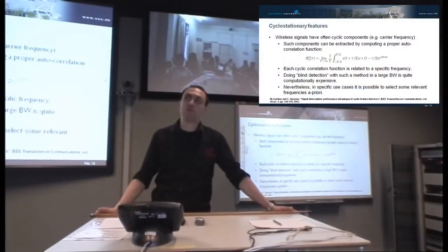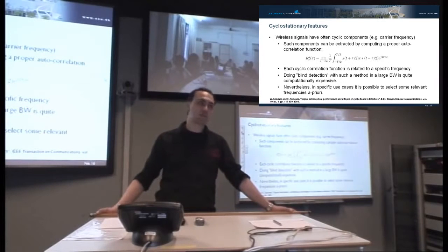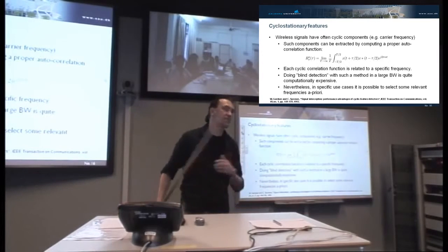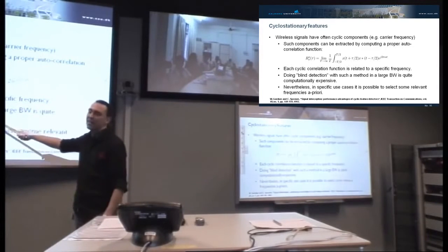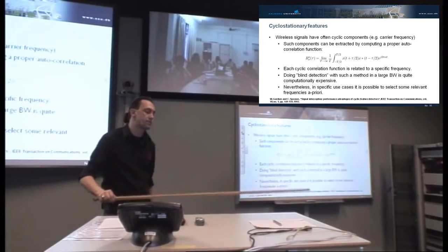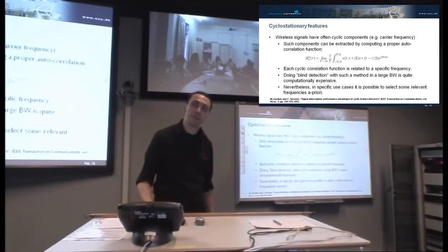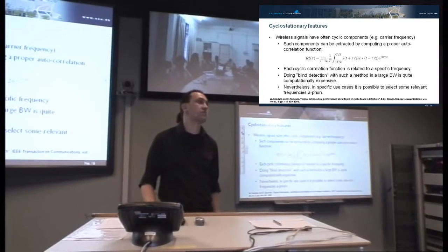If you want to do blind detection of all the cyclic frequencies, so the frequency which is always there, in a wideband, forget it. Because doing blind detection with extracting this type of feature means that with a certain frequency granularity, you need to repeat the same thing hundreds of times. Computationally it's very expensive and it's not worth the effort because you can have a more synthetic representation of what you're looking for.